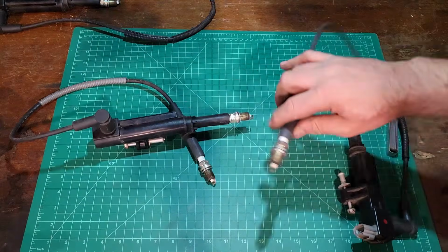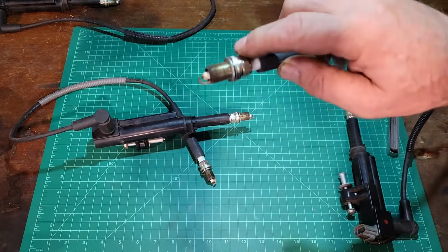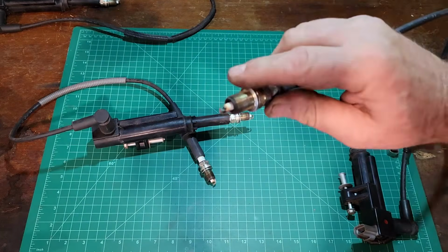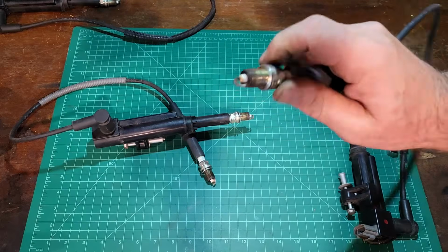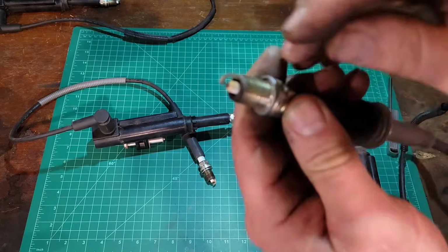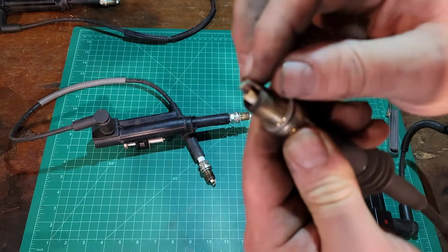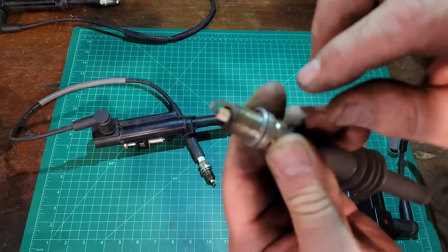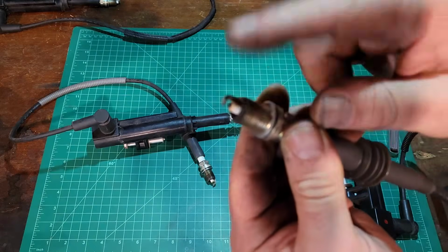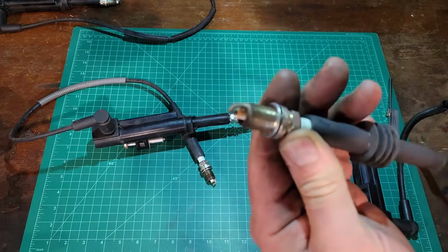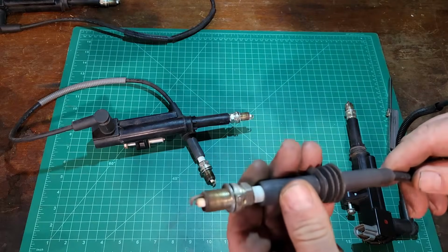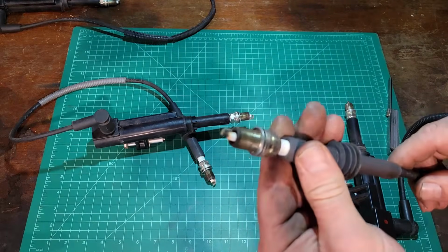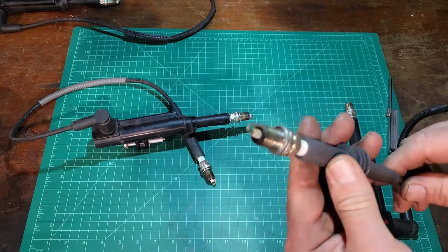The way it's looking, as new as these plugs are, you're not supposed to gap old plugs or re-gap iridiums or anything new. But you want to make sure if you do, I'll show you how with a little pair of pliers. These are so new that I'll take a chance re-gapping them because it's that close. We'll just set it right. We'll see if that fuel trim changes.